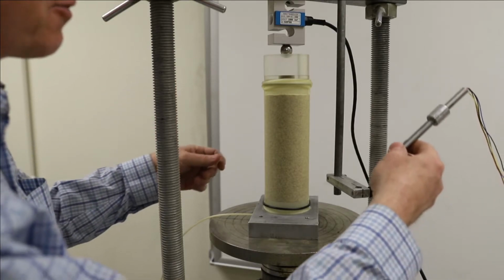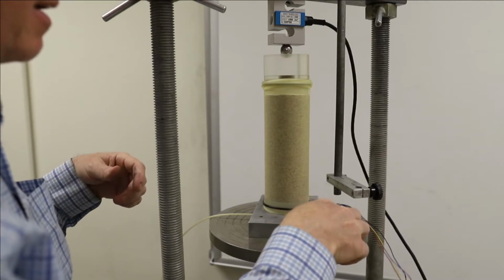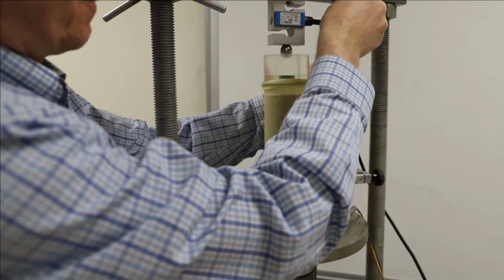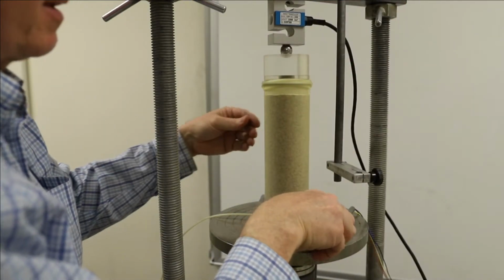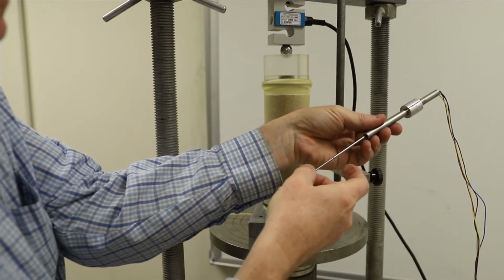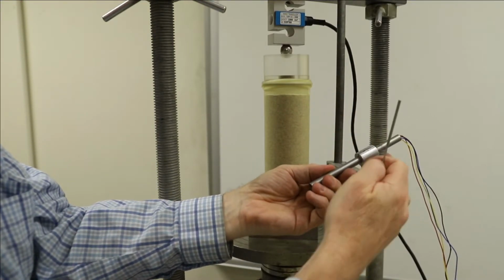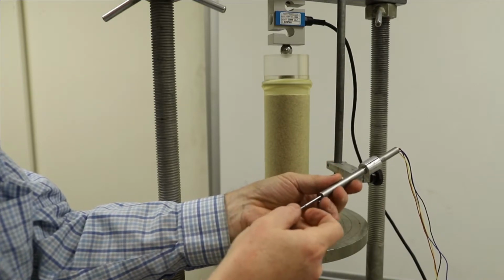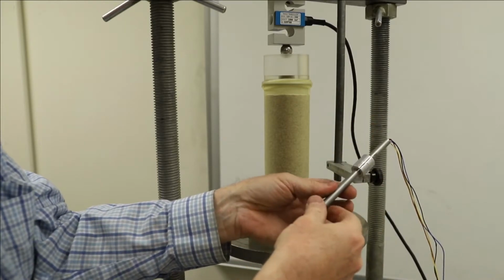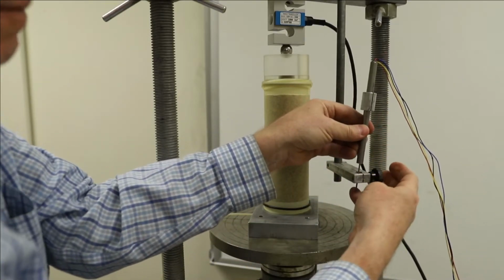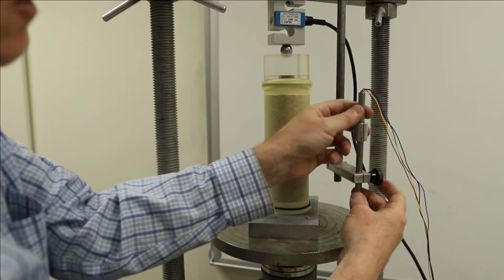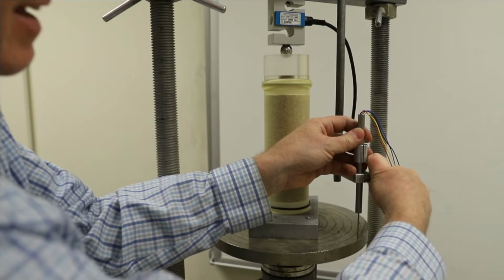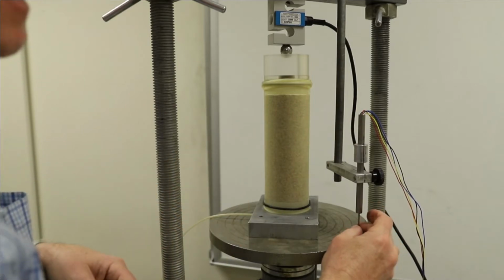In order to measure the displacements, we're going to put in an LVDT, a linear variable differential transformer, and that's going to fit in right here. That consists of a housing on the outside and a removable core, and it's a magnetic system, so there's high frequency signal in coils within that housing, and depending on where the magnetic core is, we get a different DC voltage out of it.